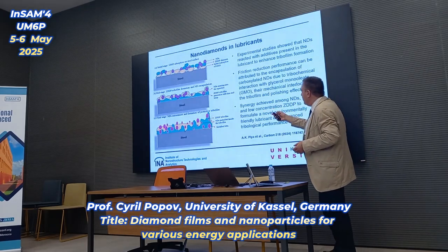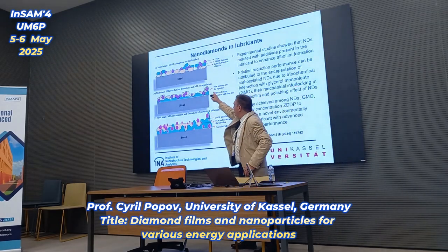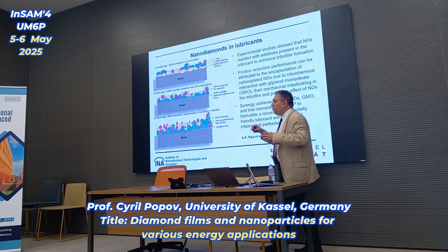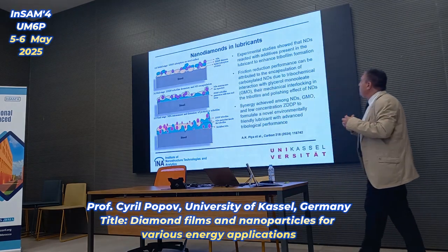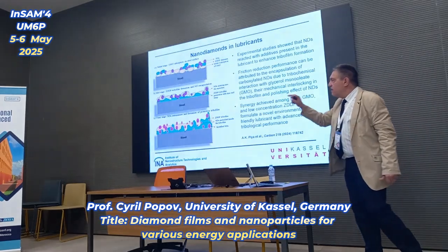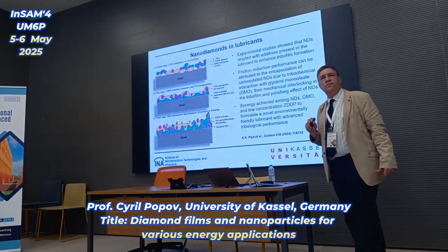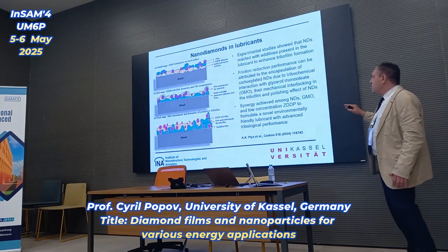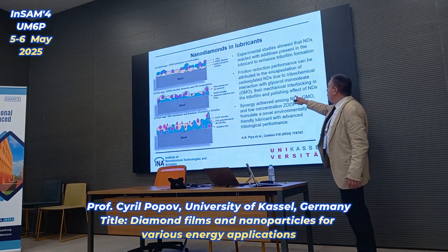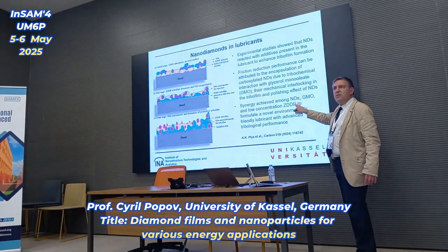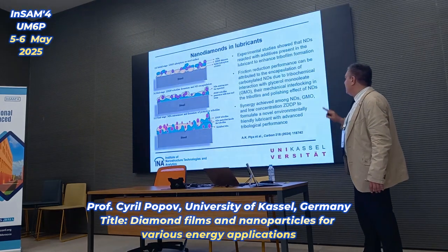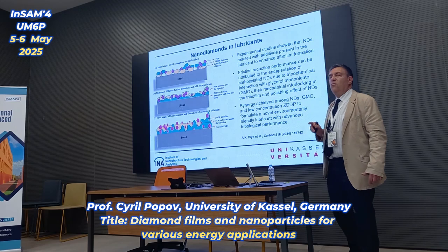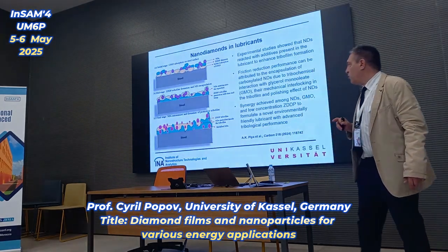They're encapsulated in the course of the process. So this is a diamond, they're encapsulated, and then they form this tribofilm on the surface of the steel part in the turbine. And in this way, this synergy is achieved between the diamond nanoparticles and the organic modifiers to form such a novel, environmentally friendly lubricant which has advanced rheological properties.